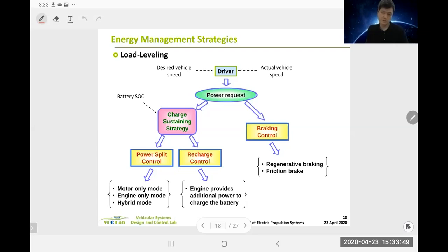It's similar conceptually, right? If you have a low SOC, then you should charge. If you have high SOC, you should use more engine. If power demand is low, then EV mode is better. If you have high power demand, then battery and motor should help, right?